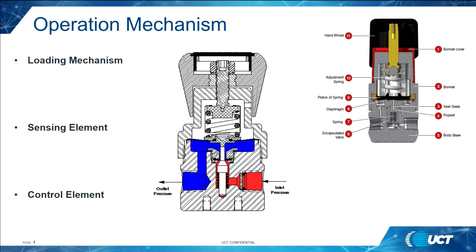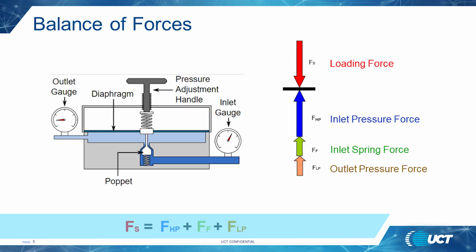Let's review the forces. In the middle, there is a diaphragm which balances all forces. On one side, there is the spring force of the loading mechanism, and on the other side, there are internal forces: inlet pressure, outlet pressure, and the poppet spring force.